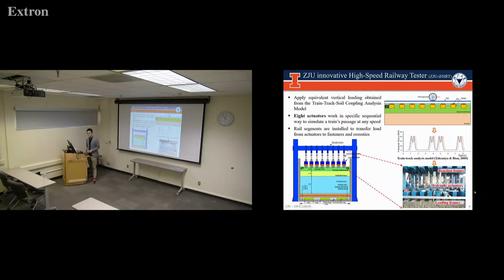Because let's suppose you have a weaker material underneath it. It might create some dynamic loading, not dynamic in the sense of dynamic analysis in which the loading is a pulse, but as a load that might increase, especially for high speed. You are right. That's why we have the PID control, to make sure the force we apply is the same as what we get from the reaction force. We apply the PID control in our DEM, and also in the actuator in the lab test, they have the PID servo to control that we apply the force we want and get the same reaction force.